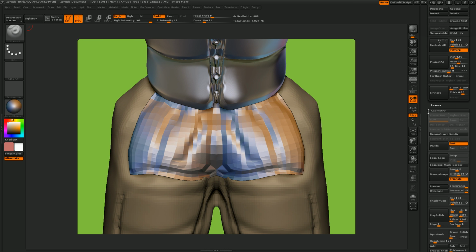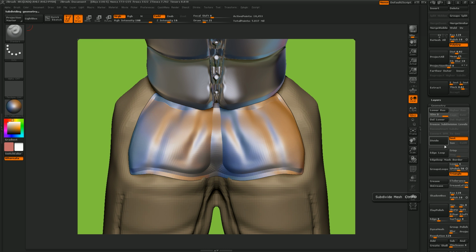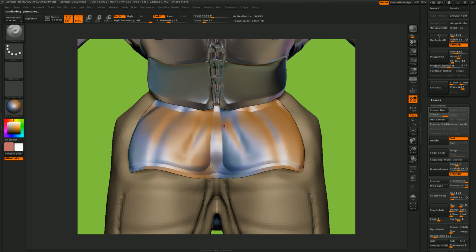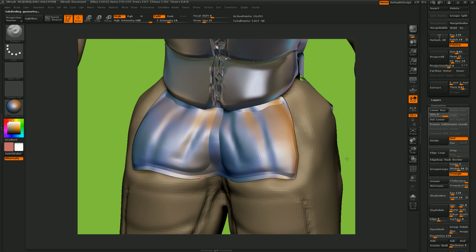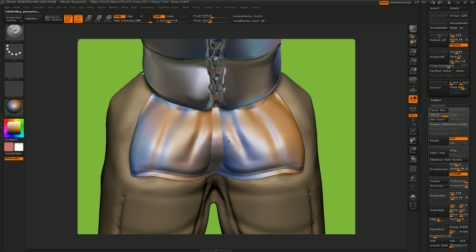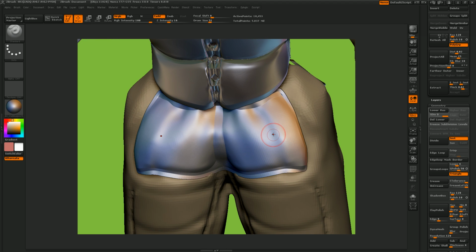And now when I divide, you can see it's kept these hard edges from the crease tool in Maya, which is a lot better than the chamfer tool in Max, because for some reason Max likes to make a mess of it. I've tried that, so Maya's the way to go, using the Proxy crease tool on selected edges.